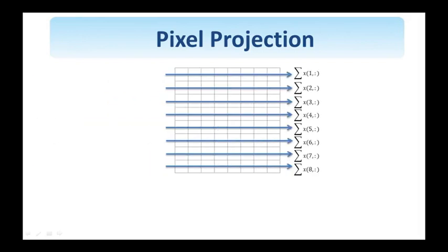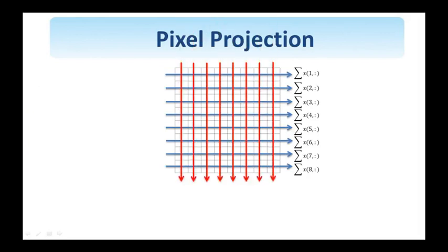And yet, as a final example of a method for reducing computations, shown here, again for an 8x8 block we would like to match, instead of using all 64 pixel values in the evaluation of the matching error, the projections of the rows, as shown here, so the sum of the intensity values in each row, as well as the projection of the columns, the sum of the values along a column, are used. So in this particular example, instead of comparing 64 numbers for finding the error, we compare only 16 numbers, and clearly there's a major reduction in computations.